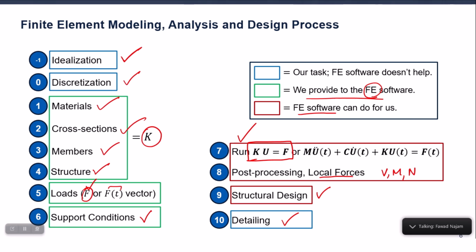So, it means that today we should focus only on these 4 things: how for a given beam, column or frame we can provide these 4 things to the program. Then we will apply some loading to it, we will define some support conditions for that structure, and then hit run analysis, and it should readily give us the bending moment diagram, shear force diagram, deflected shape, rotations, strains, and the list of all the analysis outputs, right.